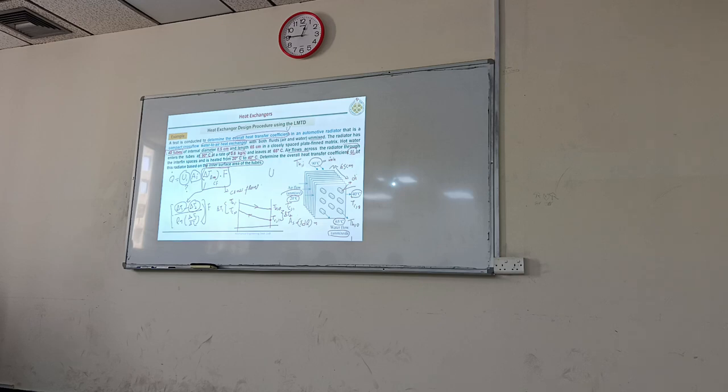Yes, now we'll see F. AI is clear. Q dot: MCP product is given for water side. This 0.6 kilograms per second is given for water. M dot H is given, so we can find out Q dot: M dot H, CPH, delta T of hot fluid. So the only thing remaining is now F, because it's a cross flow heat exchanger.